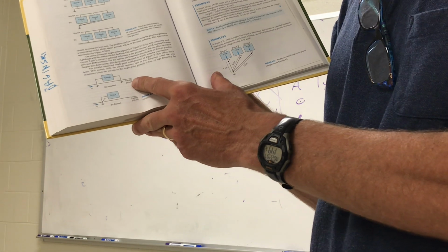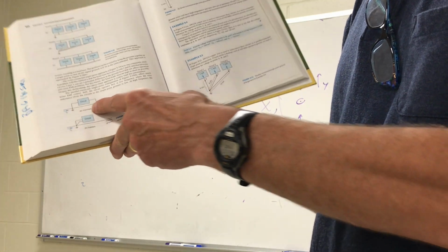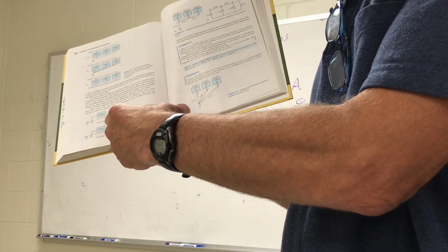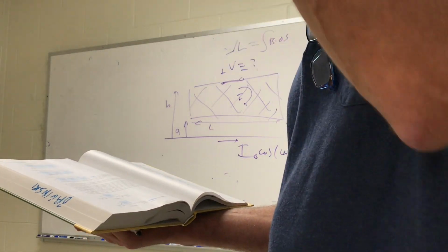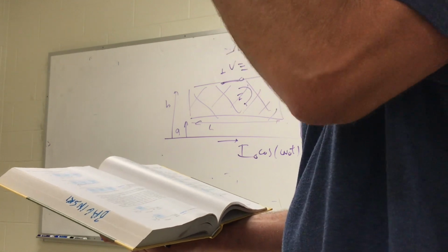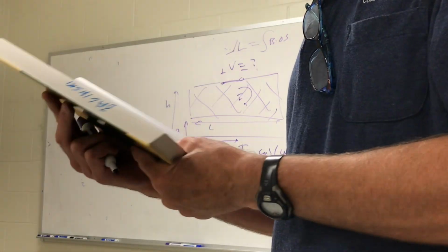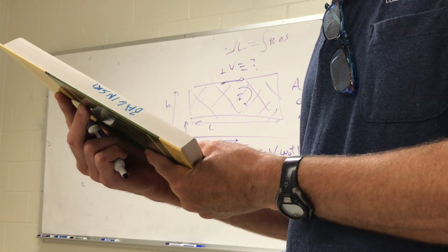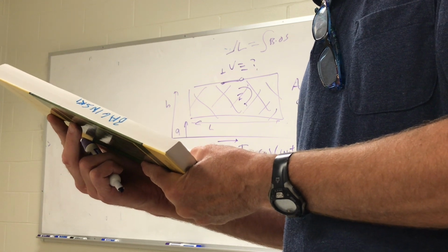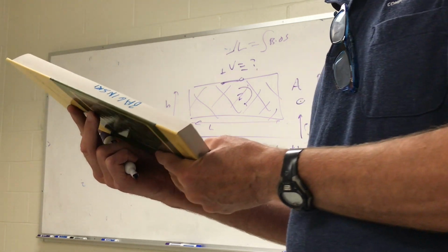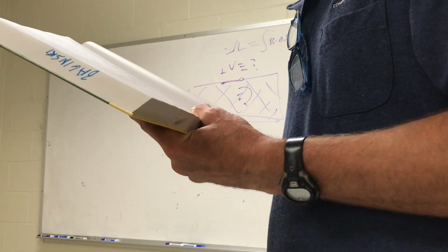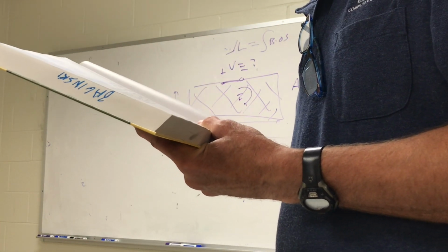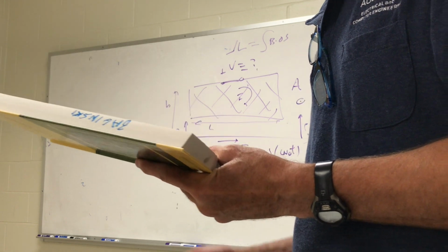thing to do. Where you put it on either side of a chassis like that, and because you got a ground loop, you also have currents flowing in the ground. It'll flow up through the ground in your device and down. So if you look at the bottom of page 522, he'll show you that. He talks about some other things with grounds. Single point grounds are the way to go. Typically, there are exceptions, but usually at that point there are tricks that he doesn't cover in the book about how to prevent problems. Grounding is a real problem.